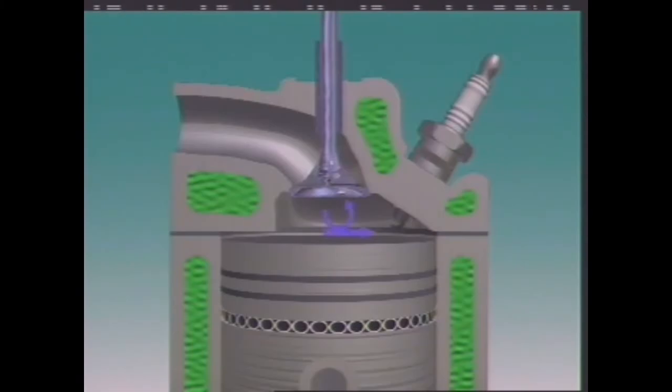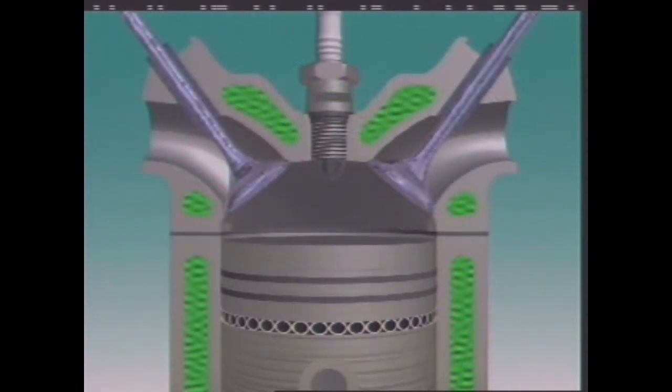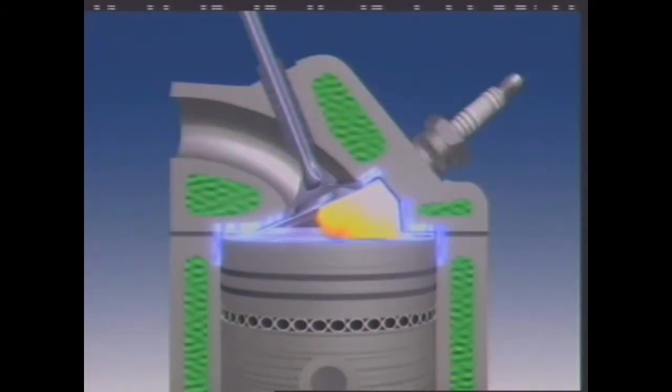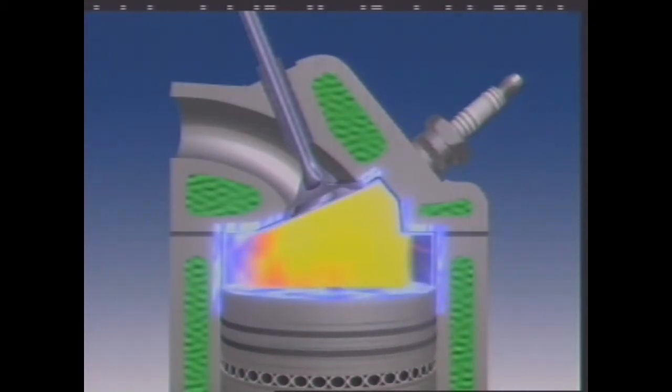Combustion chamber design can affect the combustion process also, and therefore the level of emissions. Designs that increase gas flow rate and promote vaporization distribute the fuel more evenly in the combustion chamber. Quenching of the combustion flame can occur in zones in the combustion chamber where surface temperatures are low.